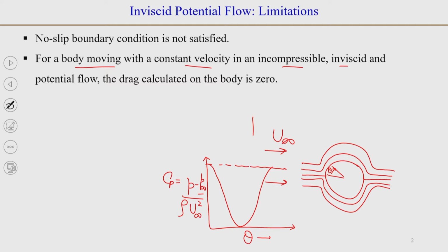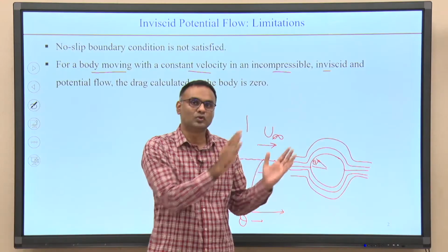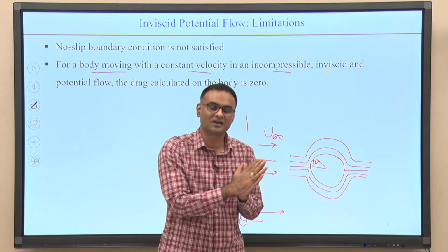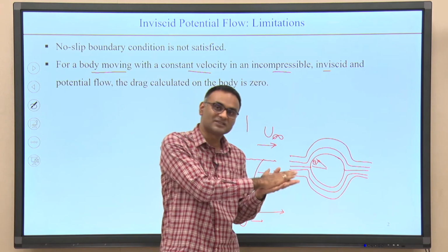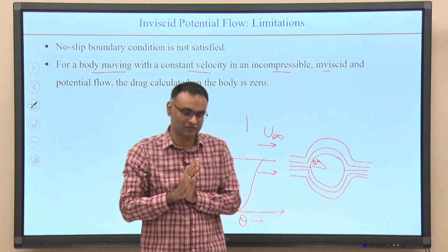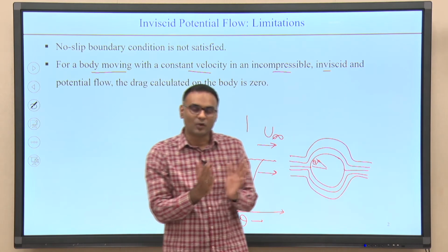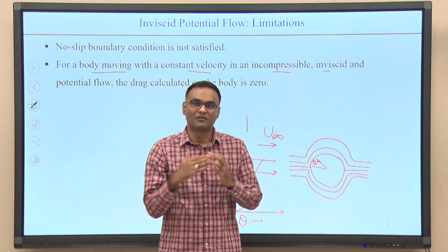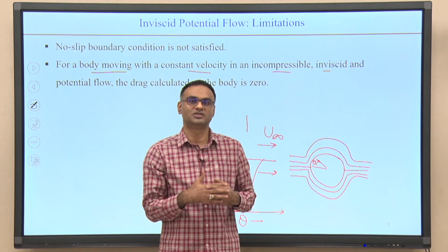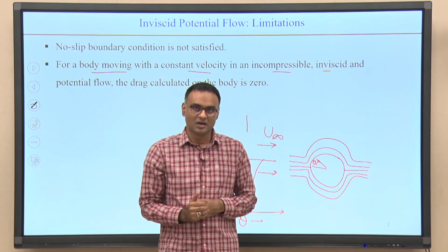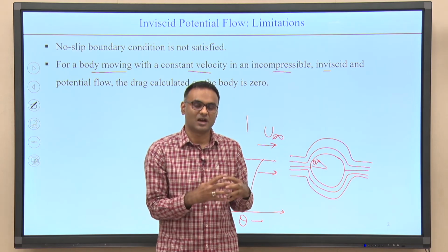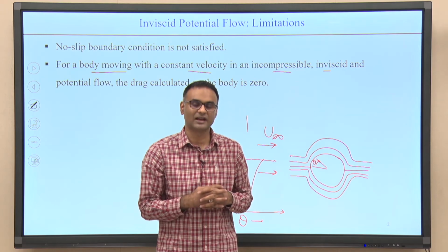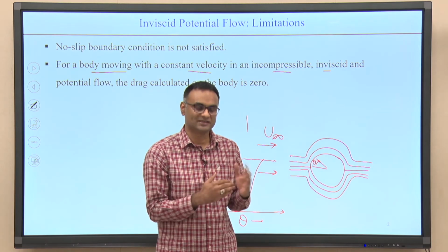So, the drag can come because of two components. It can come because of the pressure forces or because of the viscous forces. As the flow is inviscid, viscosity is assumed to be 0, or viscous terms in the Navier-Stokes equations are neglected. So, there is no viscous drag.